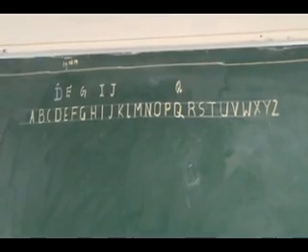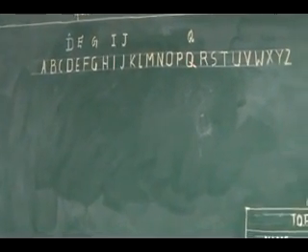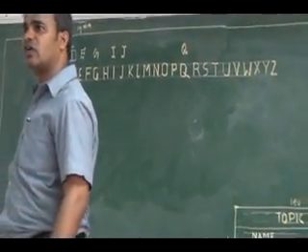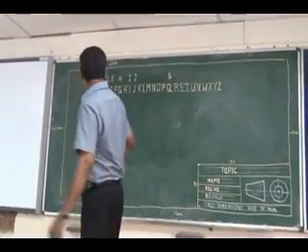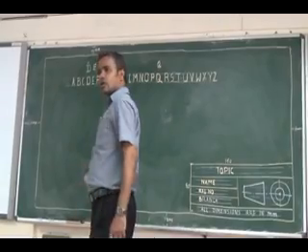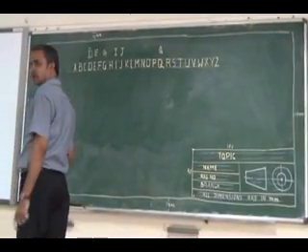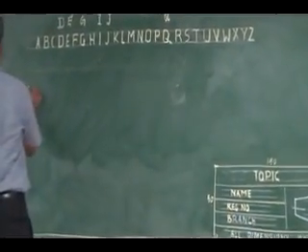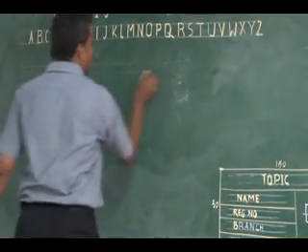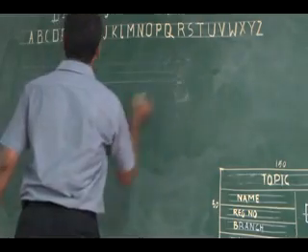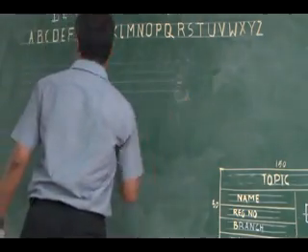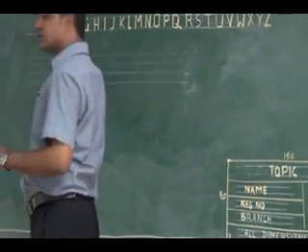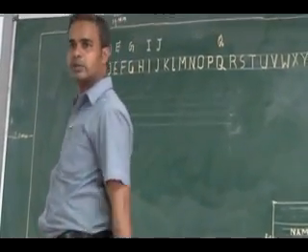Whatever you are going to write in your drawing sheet, you should follow that. The standard font is Gothic, I think. Then, to write in small letters, you have to put 4 lines at a convenient height. Overall, this will be 5 mm, and over that you can have 2.5, 2.5. Overall 10 mm you can have.